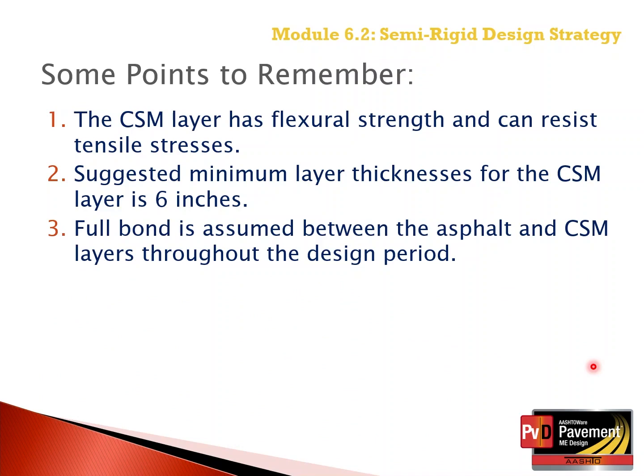So remember, if the user or designer wants to assume lower bond or no bond between the asphalt and the chemically stabilized layer, that is possible through the layer interface. But for calibration, full bond was used in all cases for new construction.